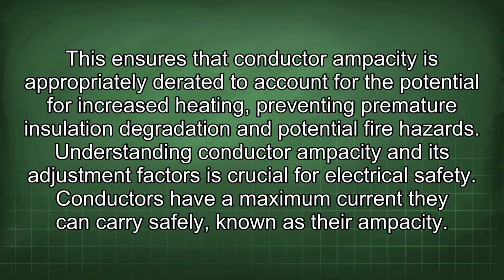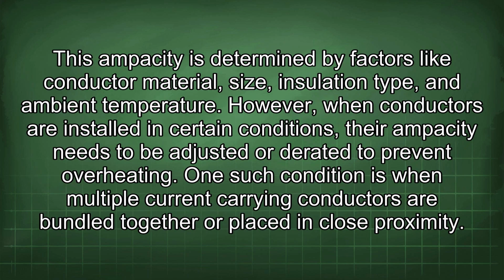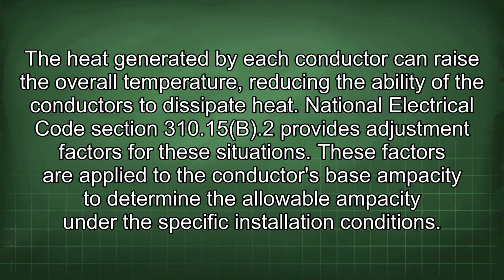Conductors have a maximum current they can carry safely, known as their ampacity. This ampacity is determined by factors like conductor material, size, insulation type, and ambient temperature. However, when conductors are installed in certain conditions, their ampacity needs to be adjusted or derated to prevent overheating. One such condition is when multiple current-carrying conductors are bundled together or placed in close proximity. The heat generated by each conductor can raise the overall temperature, reducing the ability of the conductors to dissipate heat.